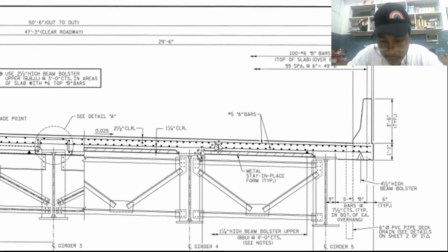Take note of this. We have the principle of reinforced concrete. I will talk about this. That's why please remember this. At the point where the concrete is directly above the girder, there is no bottom reinforcement. There is top reinforcement, but there is no bottom reinforcement. Take note about that.